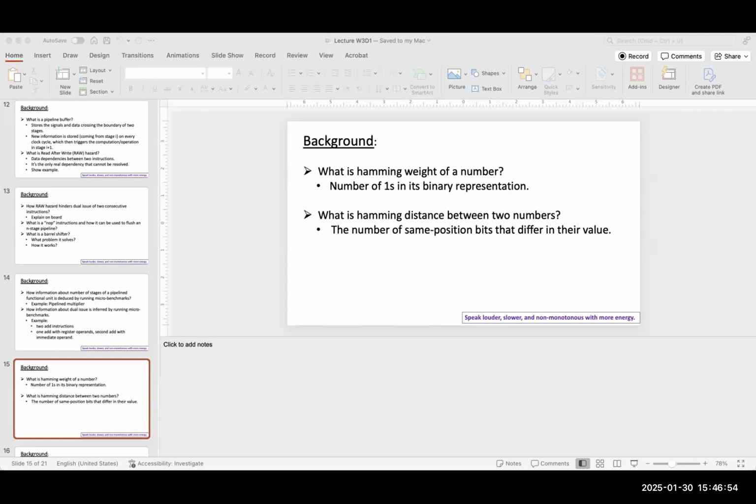You would be able to dual issue, say, the multiply, since you can have one multiply on the first ALU and the other on the other one. Then we will be able to dual issue, and we will have a better CPI, for example 0.5. Again, if everything else works, let's say your register file supports it, so you can read all the operands of two instructions at the same time, and you have two ALUs, both identical, both can do the multiplication, you can issue two multiply instructions at the same time, right? But if you go back to this table, a multiply instruction cannot be dual issued with another multiply instruction in this case.